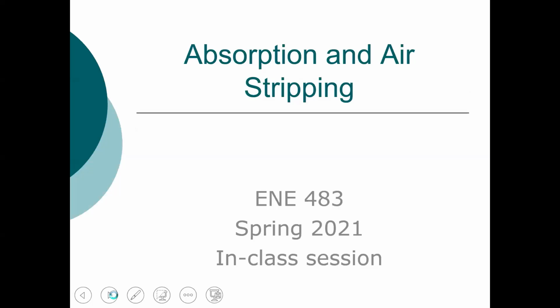What we will do is we'll finish the unit today on absorption and air stripping. I have posted 2 videos from Wednesday and Friday. Wednesday's video really focuses on the theory of absorption along with an example problem on aeration of a pond, mechanical aeration. And Friday's lecture focuses on actually DO sag curves, Streeter-Phelps equations, includes some material from the FE reference handbook.